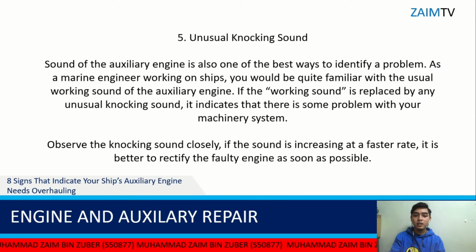The fifth sign is unusual knocking sound. Sound of the auxiliary engine is also one of the best ways to identify a problem. As a marine engineer working on ship, you will be quite familiar with the usual working sound of the auxiliary engine. If the working sound is replaced by any unusual knocking sounds, it indicates that there is some problem with your machinery system. Observe the knocking sounds closely. If the sound is increasing at a faster rate, it is better to rectify the faulty engine as soon as possible.